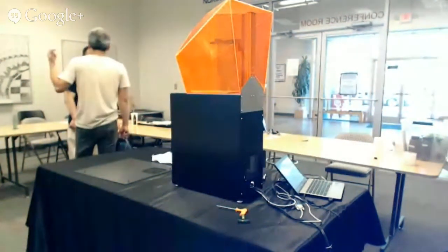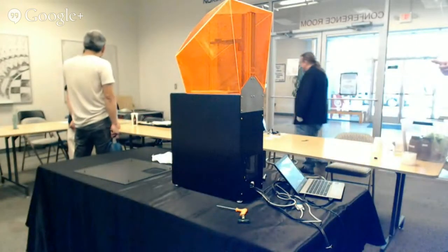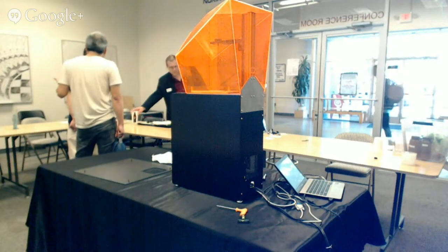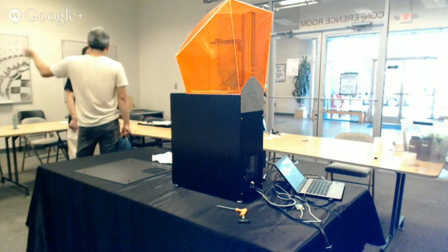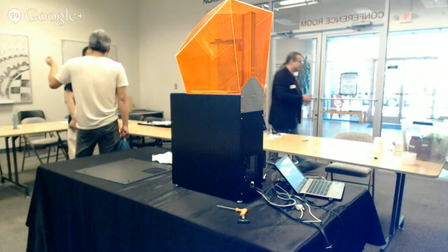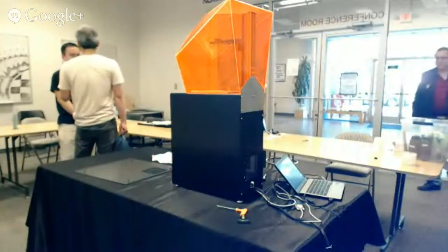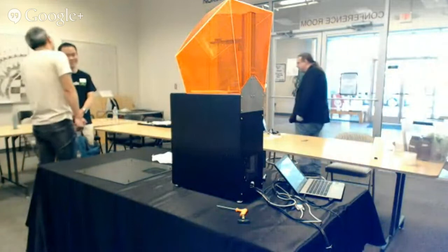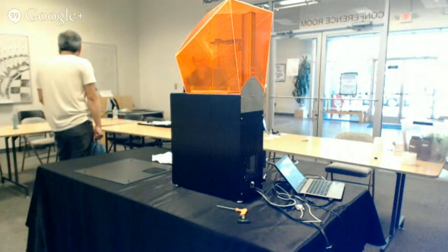Probably, yeah. That's what it's really made for. It helps conduct the heat. You're not so worried that it's not tough enough; you're worried that it will soften because of the heat of the plastic. The plastic comes out at like 350 degrees. 350 degrees is enough to warp even this thermoplastic, but because you have a big mass, and I'm only injecting a very, very small amount of plastic compared to the overall mass,